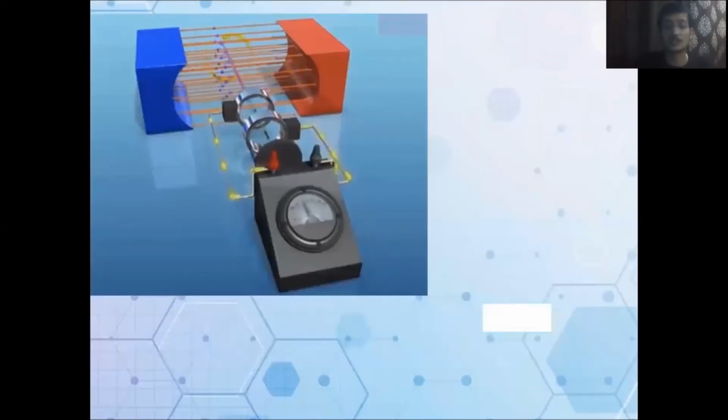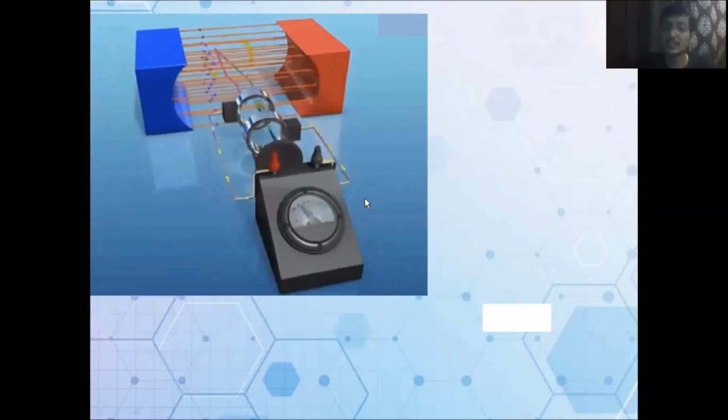Here you can see how a generator coil rotates. One end of your coil is always connected to one ring and the second end is always connected to the other ring. It's just like they are touching and rotating. So here you can see the armature is rotating in one direction, but continuously we are getting the current in two directions, from left to right and then right to left. This galvanometer deflection shows which side the current is flowing.